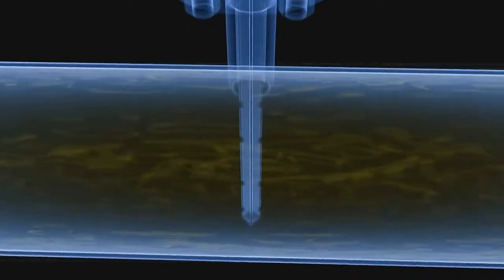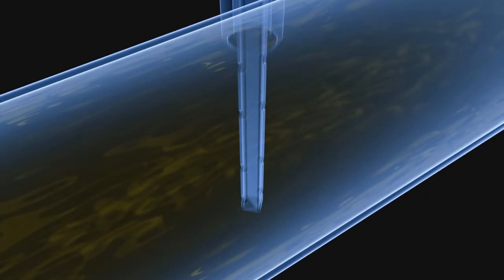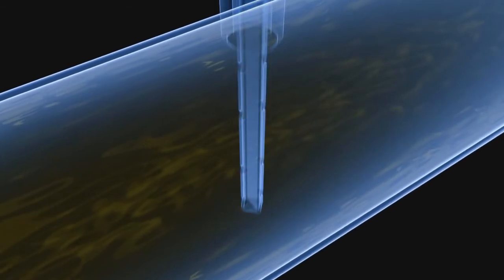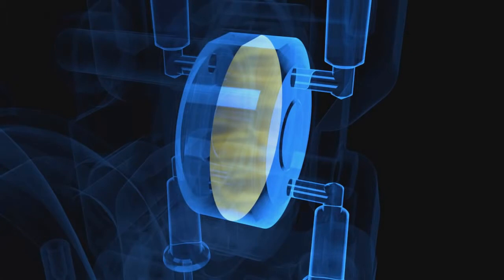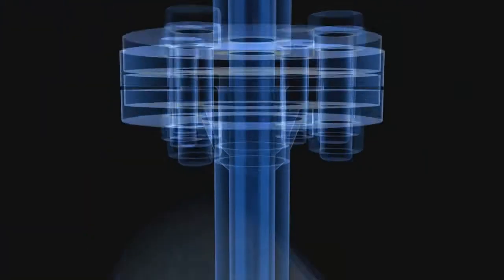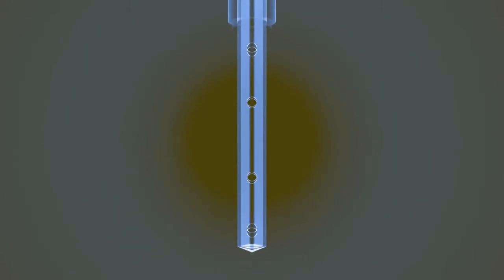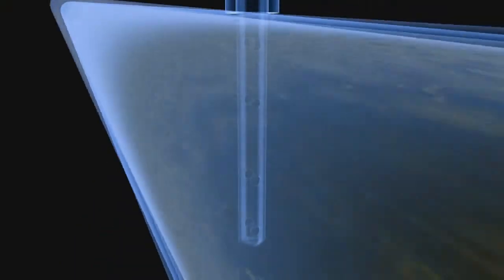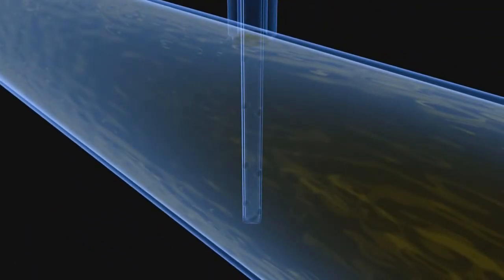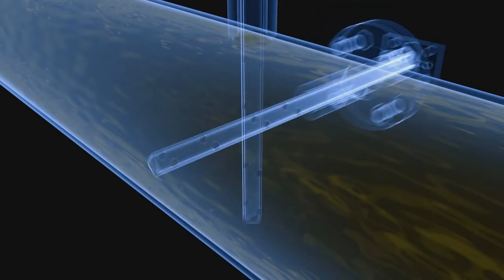Pitot tubes have a rod-shaped measuring element that is inserted into the pipeline perpendicular to the flow direction. On the front and rear of this probe are several holes. Two separate tubes connect these holes to a differential pressure sensor. With its two pressure chambers, separated by a diaphragm, the tiniest pressure differences in the flowing fluid can be precisely measured. The individual pressure taps are distributed along the entire pipe cross-section to ensure a representative measurement. If there is strong interference in the flow profiles, it's advisable to fit a second pitot tube, rotated by 90 degrees.